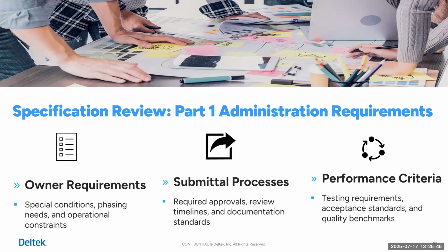Well, it's in the spec that way because someone did not let the specifier know, oh, by the way, all we need is product data. We don't need a sample of type X gypsum board. Now, there might be some projects where an owner or facility may want these different samples, but in general, those types of samples for gypsum board are not required. But how would the contractor know that if that wasn't coordinated ahead of time? That was just an example.